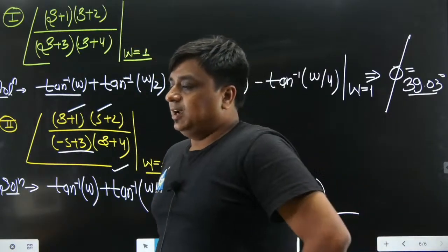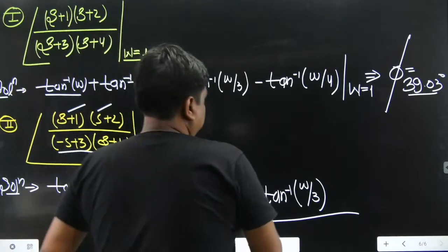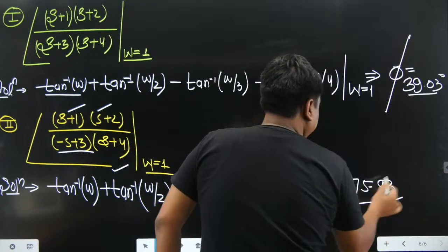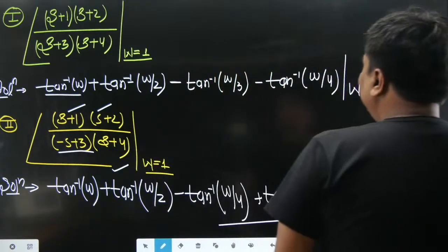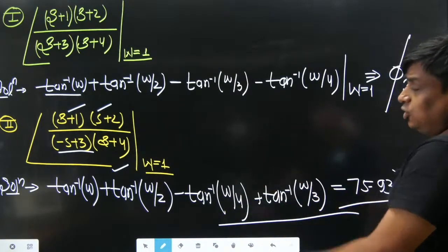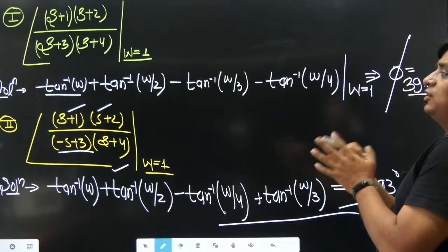How much angle have we been getting? Excellent, Khanam. According to Khanam, the answer we have been getting is 75.93 degrees somewhere. So what I am saying is, in future, be ready. Probably the magnitude would not be your problem. The angle is going to be the actual crux or actual pain, at least over the Nyquist as well as Bode plot.